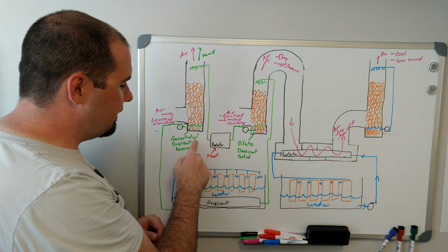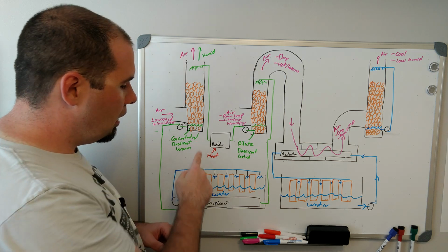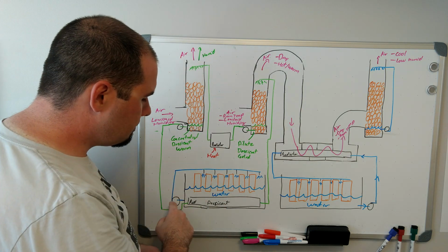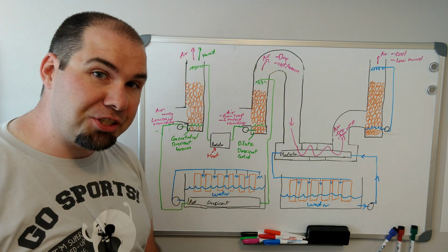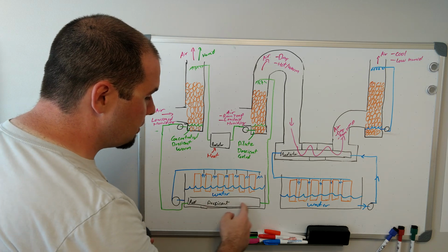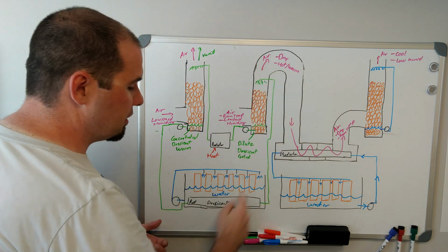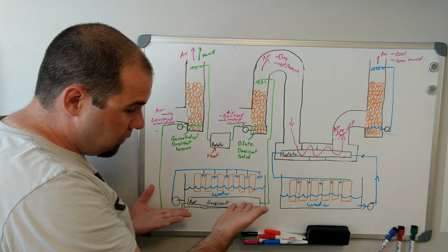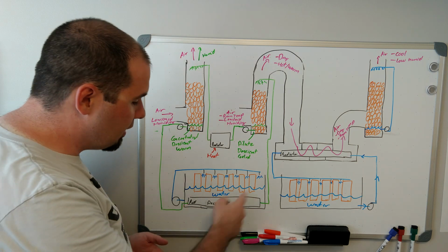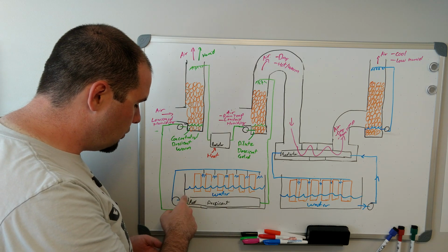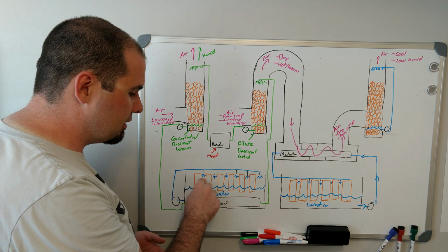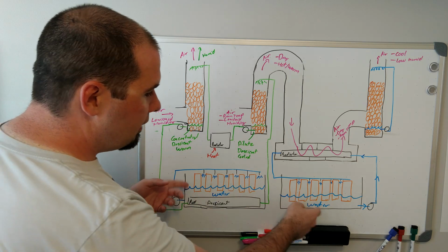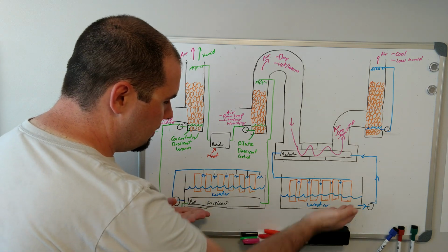So through this process, it leaves us with concentrated desiccant, but that desiccant is still warm because we had to heat it up. So we run it through another heat exchange process through a radiator, just with the desiccant in it to cool it for this process. And to cool the radiator, there's several different ways, but the way he used was another swamp cooler that recycled onto itself. So this water is cooled, goes up, it sprays it on these foam blocks, and then they evaporate, cooling. So these water supplies, as he mentioned, will drop.